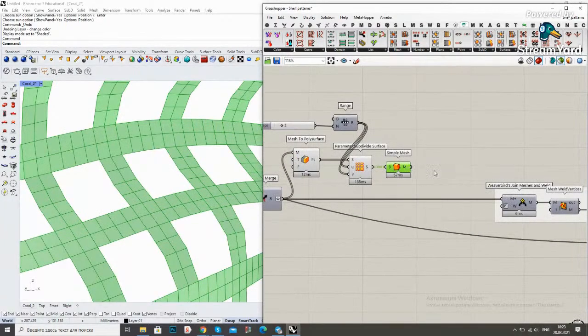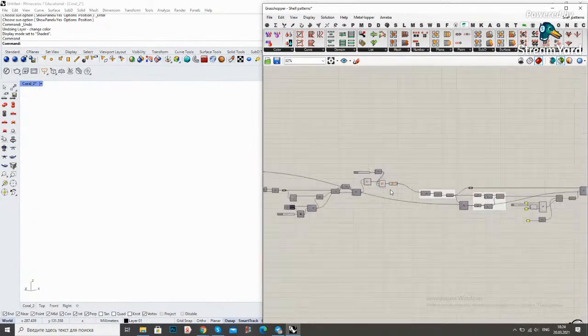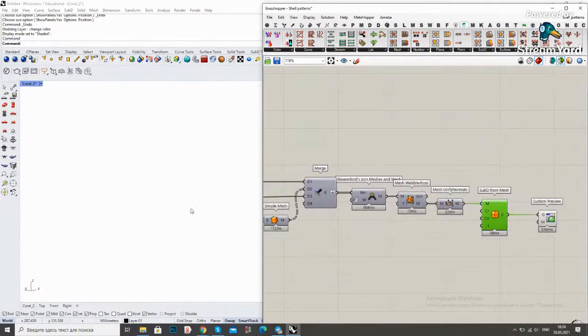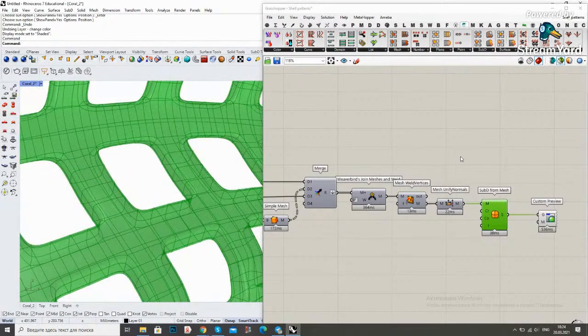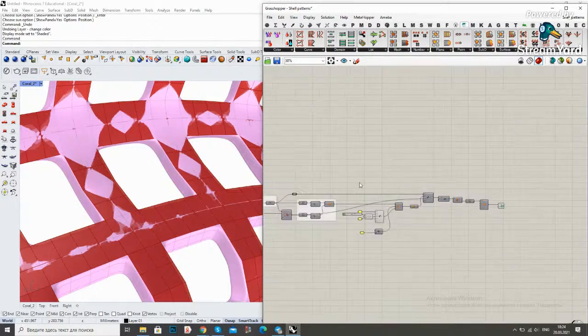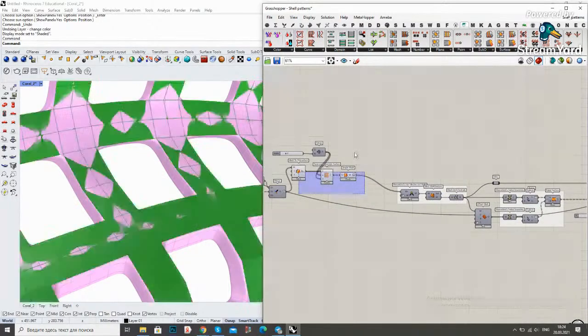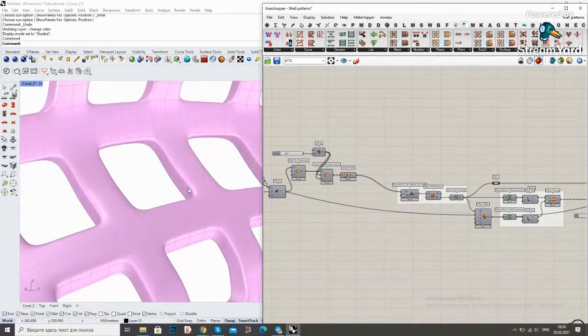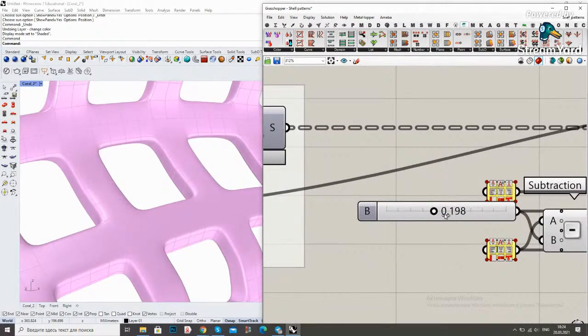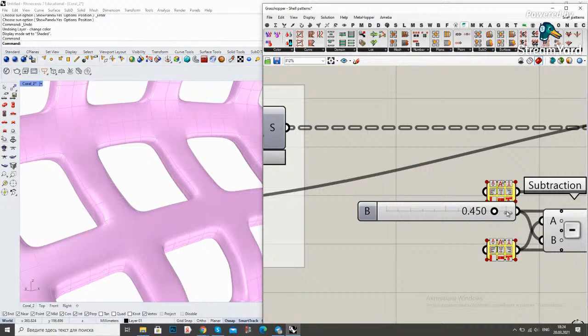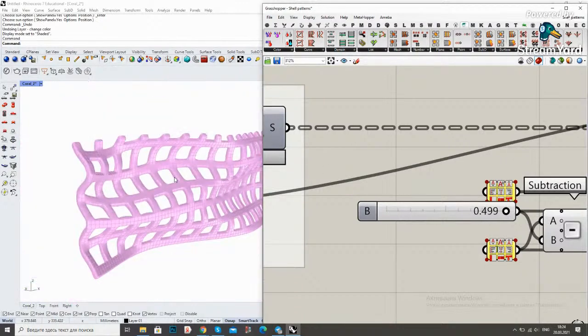We flatten it and we connect it to the Weaverbird join meshes and weld. And I guess now we get something better. Yeah, so now, as you can see, our shape will not lose its sharp edges as much as it did before. See, it preserves part of its shape, but it becomes more smooth.